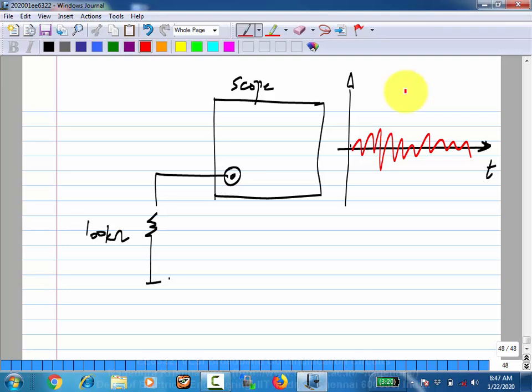So 4kT R times the terahertz limit, is that the... Yeah, so it's the oscilloscope's bandwidth, right? The oscilloscope will have some bandwidth. Let's assume it's an abrupt filter. So basically you will see 4kTR times the bandwidth. This is the variance of that noise. So how much will that be? Let's say the bandwidth is 100 megahertz.